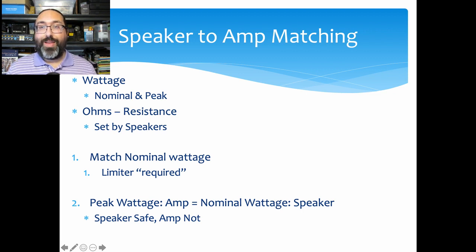If you try to do that, you could clip that amplifier, which will then send that clipped signal to the speaker, which will then send a really nasty DC signal to the speaker, and then your driver will go all the way in or all the way out, depending on which phase it is at that specific moment. And then you can also blow your speaker. So you are looking to keep these within at least a couple hundred watts, within that 10% range. But this is the way to make sure you're less likely to blow your speaker.